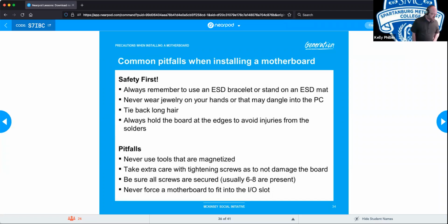One other thing that I would suggest, if you are ever opening up and going into any kind of electronic, be it a computer, a mobile device, a laptop, what have you, as you are unscrewing the screws, make yourself what's called a screw map. I actually have a mat with a bunch of indentations in it so that I can lay out the screws in the pattern in which I'm taking them out. Some people have a system to it, like they'll start at the top left corner and unscrew everything in a clockwise fashion. Whatever method you have, find one that works for you, but find a way to keep track of these screws as you're taking them out so that when you put them back, they go in the right place.